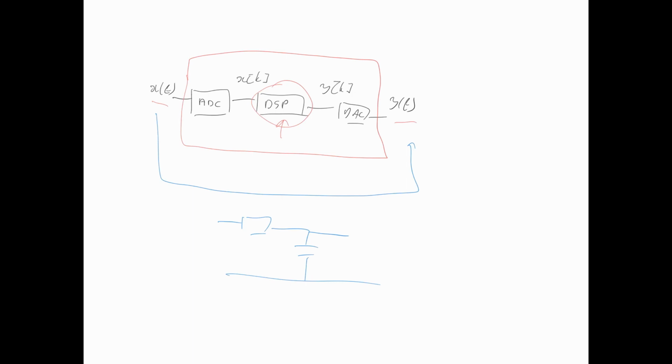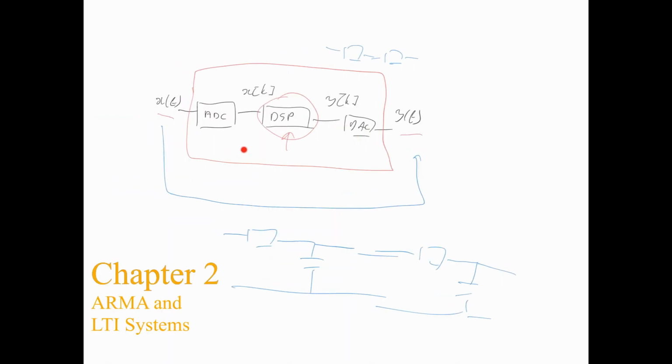Their design is somewhat complicated because if you add a second low-pass filter in front of this first one, then the impedance of each of these low-pass filters affects the other. Whereas in the digital domain, we'll find out later that if we put two filters, one after the other, then there is no interference between the two filters and they function the same as if they were on their own, so to speak.